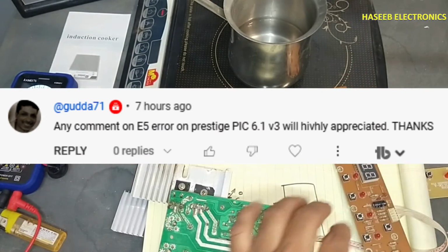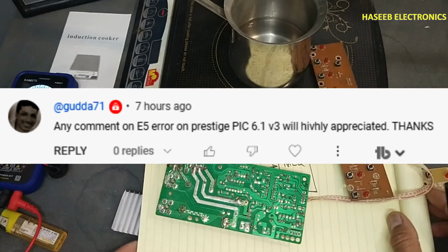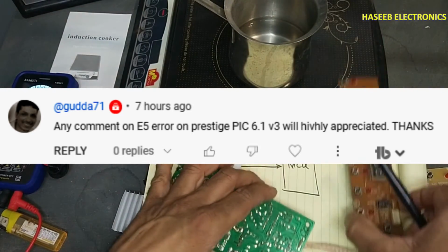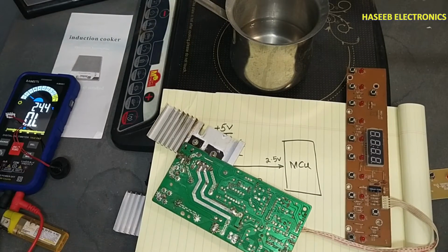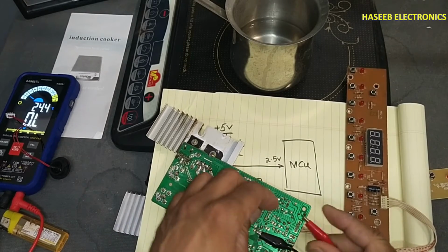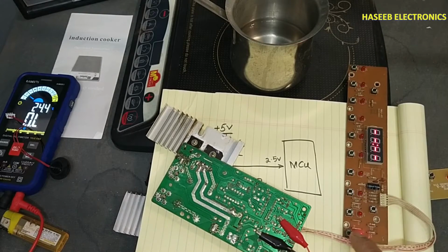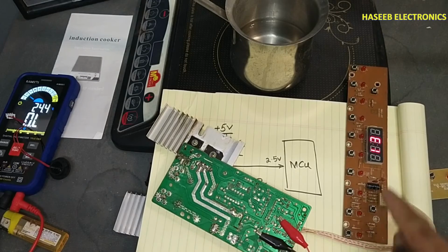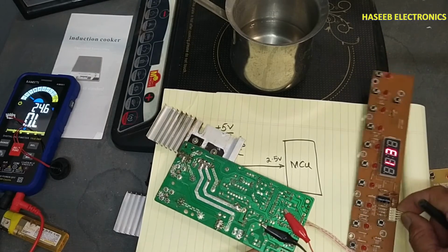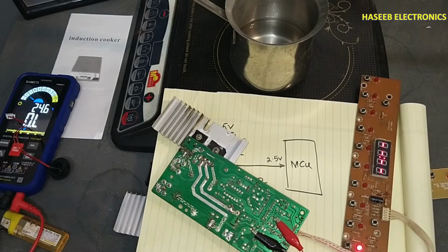Basically, it is a question from my viewer to discuss E5 error in Prestige induction cooker. What will the condition be? Now I will show here. It's ground, and here I am connecting 5 volt. This time it's showing E1 error because I'm not connecting the induction coil.